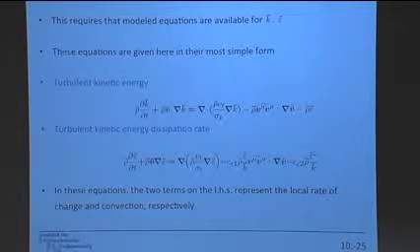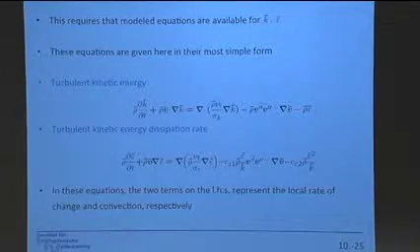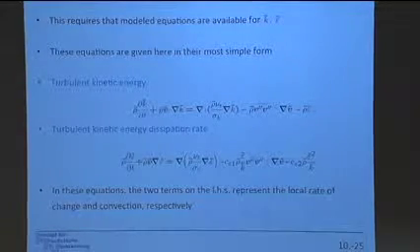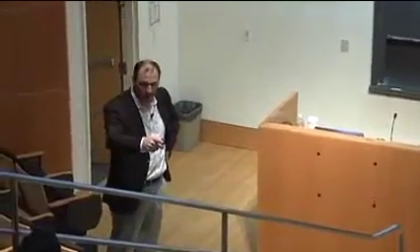The other thing is this here is now minus this epsilon term. Epsilon is a quantity that is kind of a velocity gradient squared. So that's why we call it the dissipation rate. Remember earlier we called it the scalar dissipation rate, or the dissipation rate of mixture fraction. That was also gradient squared.